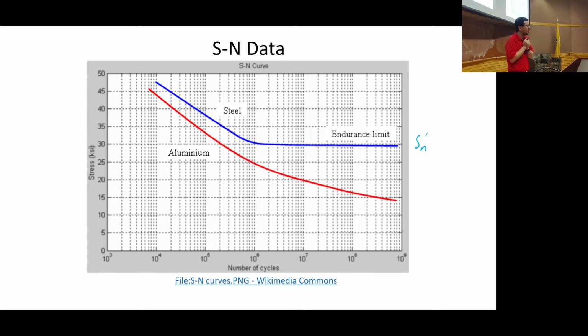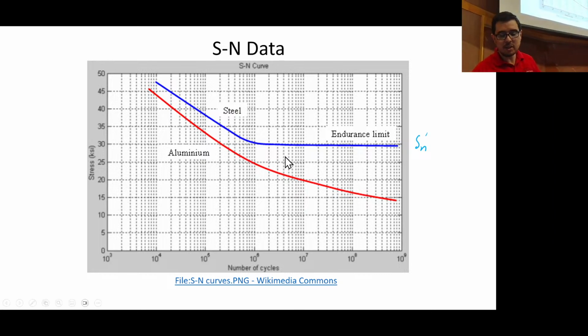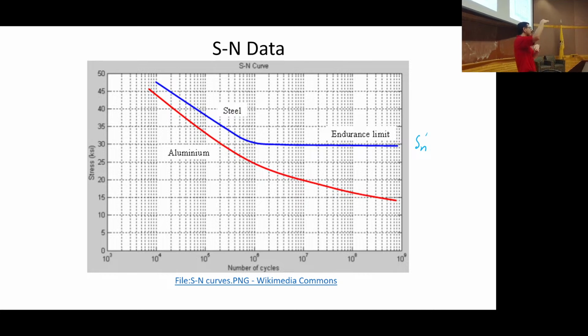Alternating stress is below the current endurance limit, no matter how many cycles you do. That's right. So typically we're trying to make sure that our alternating stresses, the magnitude of it for the fully reversed case, are below this limit. And if they are, everything is awesome. Okay? And you did good midlines and all that kind of stuff, right? And you're looking at, okay, if it's not plus or minus the same value, all those types of scenarios, right?